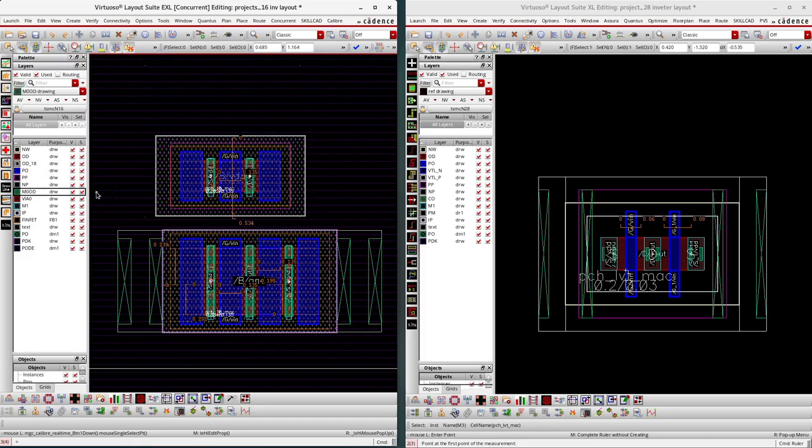So in FinFET design we have one more layer called M0 OD. This is nothing but creating a contact between the OD layer and the M1 layer. That's all. This is our base level contact, the M0 contact. But when you come to the planar MOSFET, we don't have a contact or via called M0. Directly we used to start everything from the M1 layer.